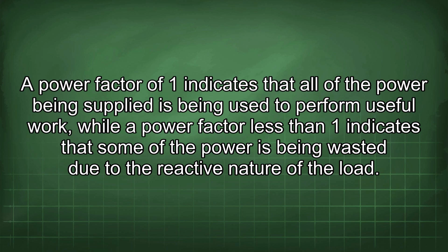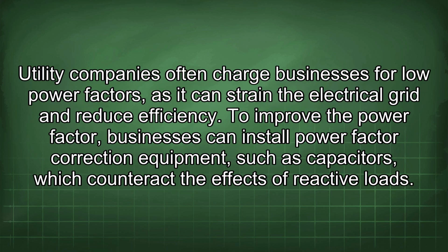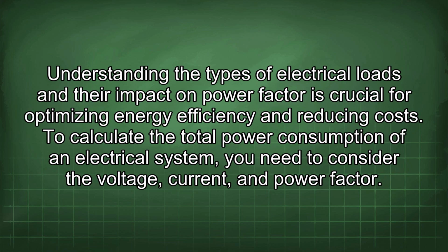nature of the load. Utility companies often charge businesses for low power factors, as it constrains the electrical grid and reduces efficiency. To improve the power factor, businesses can install power factor correction equipment, such as capacitors, which counteract the effects of reactive loads. Understanding the types of electrical loads and their impact on power factor is crucial for optimizing energy efficiency and reducing costs. To calculate the total power consumption of an electrical system, you need to consider the voltage, current, and power factor.